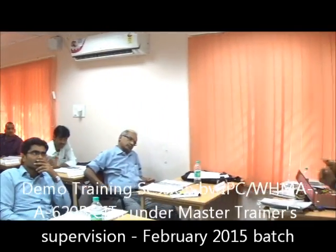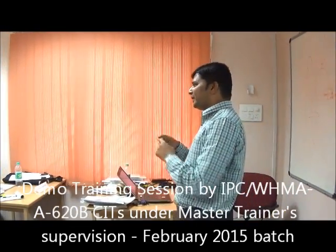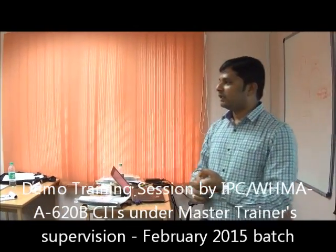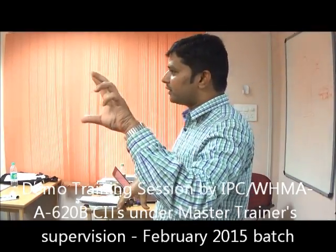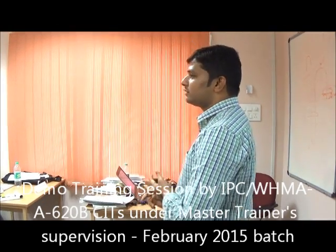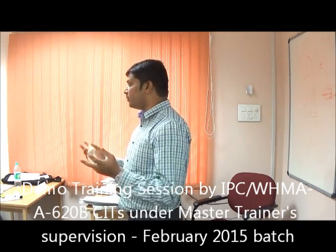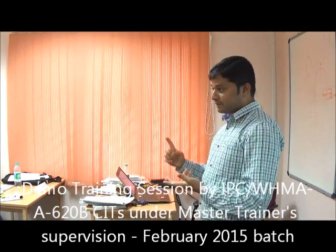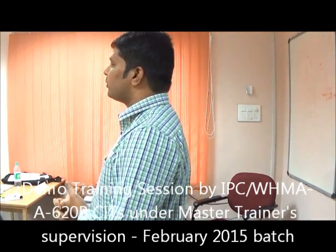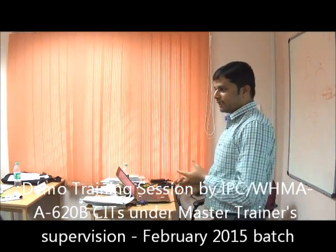Indirect is the manufacturer who makes zip connectors and wrapping. It is a part of rectangular connector. We have some more connectors like zip connectors, like zero insertion force. Just make the mating end, rotate it so that it gets locked to the mating part. And we have mass interconnect connectors, where we can interconnect around 500 to 1000 connections at a time. It may be the power, the signals, or the RF signals. Everything will be interconnected in only one part, so we call it a mass interconnect connector. So these are some of the examples of connector types.